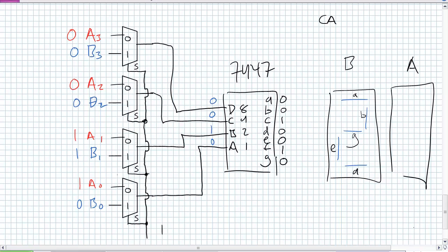So what do my outputs look like? A through G. Okay, there's my outputs for that particular display of 2. A0, B0, C1, D0, E0, F1, G0. When I'm sending that data to this 7-segment display, I should see it lit up as a 2. But be aware, I'm sending that same 7-segment data to, and I'm not going to draw all the wires, to this display right here. The deal is I'm just not enabling that one's anode.